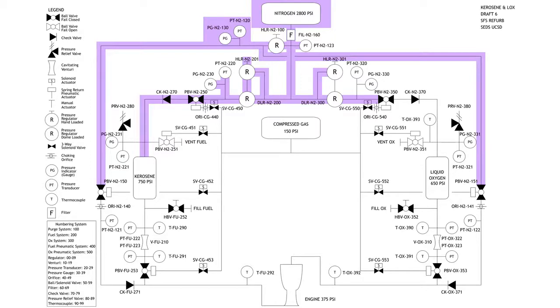All right. So that'll be slowly open, slow press. Also, one thing about this is that look at your pneumatic ball valve N2 251. That's your vent. If I were trying to pressurize my system and I had my vent open, I would literally be wasting all that nitrogen gas because it would go straight into the atmosphere. So I need to close that ball valve. So this is a closed system now.